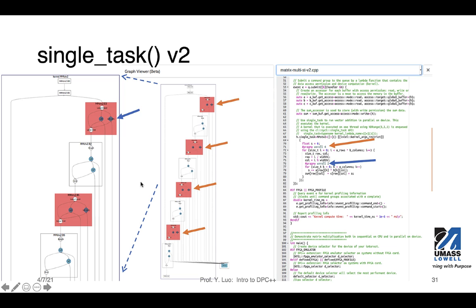So from looking at the design, and this is the whole design, we're going to see 4 of these modules because of this unroll factor of 4. And within each of these modules, we enlarge that here, you can see this 2 times load store unit, and we have 2 of those because we have an unroll factor of 2.